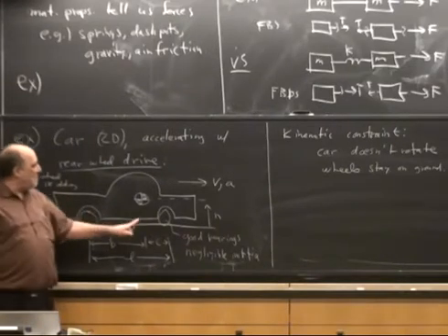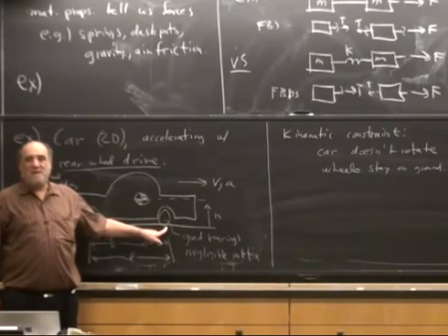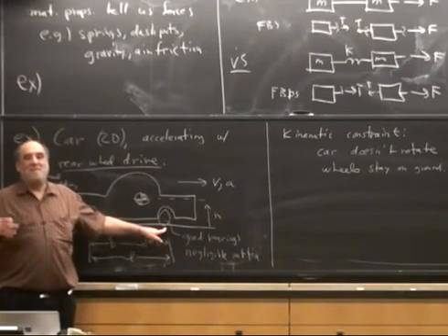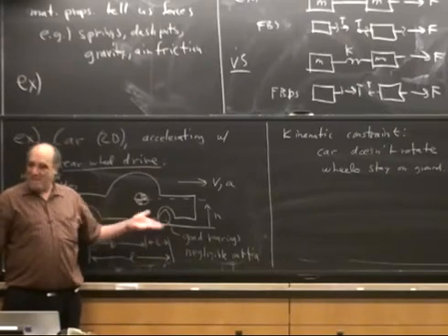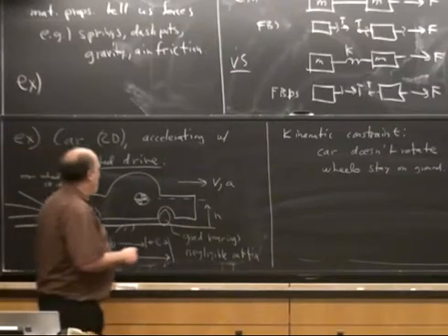How do we check that? We'll look at the reaction force here, and when we calculate this so-called constraint force, we'll make sure that it's not in tension, the ground doesn't suck. If in our calculation the ground does suck, we say we made a mistake by assuming it didn't do a wheelie, therefore it probably did do a wheelie. So without actually doing the calculation of the rotation, we can check to see if it rotates or not by assuming it doesn't, calculating the reaction force, and looking for a contradiction. If we don't find a contradiction, it didn't rotate. If we did find a contradiction, it did rotate. We did the problem wrong. Now we want to do the problem right. Well, you've got to wait a few weeks to learn how to do that. Okay, so this is how we're going to deal with this problem.